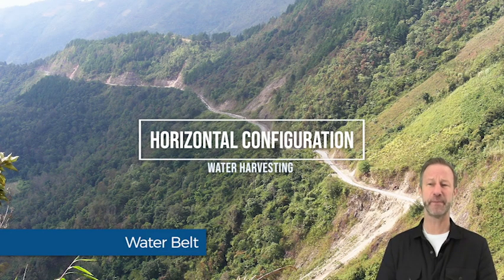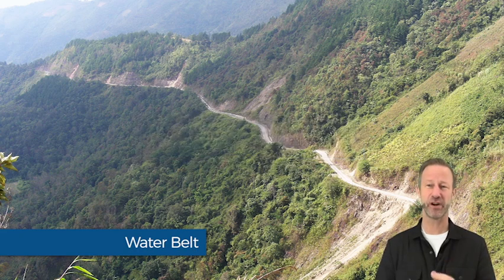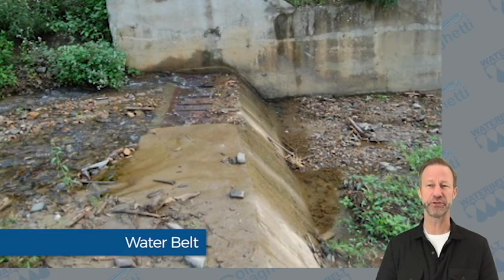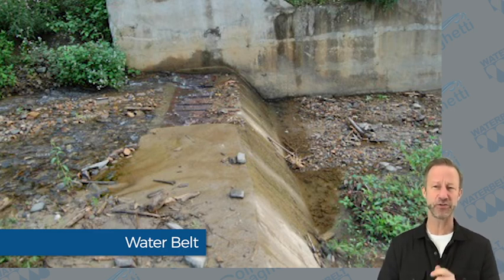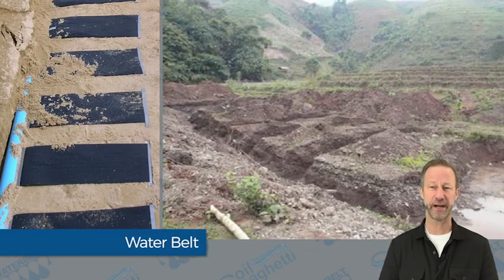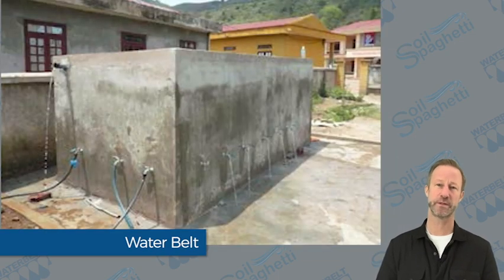Water harvesting. It's becoming increasingly important as pressure on water resources grows. In a remote mountainous region, above-ground dams built to store and supply water for small villages have been silted over and dried up. A novel solution was developed to collect water from seepage in what appeared to be a dried riverbed. Waterbelt was installed in parallel channels dug into the riverbed where there was evidence of water. The collected water was channeled into a central reservoir for distribution to the homes.